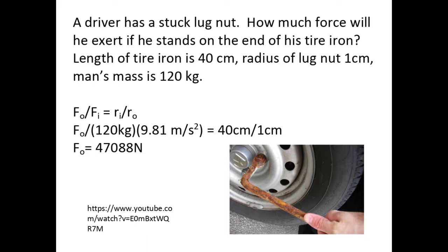And if you ever get a lug nut that won't come off, you could put a pipe around the tire iron to increase the radius, the length of the arm, and that would then give you even more force.